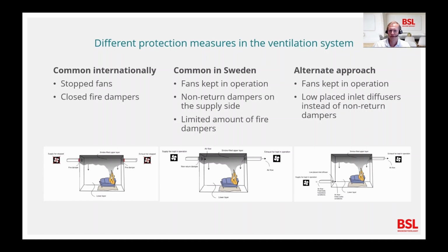However, during the last decade, an alternate approach has been examined, based on the same basic principle as the one previously mentioned. The fans are kept in operation during fire. But instead of using non-return dampers on the supply side, the supply diffusers are positioned close to the floor.